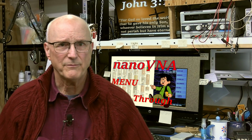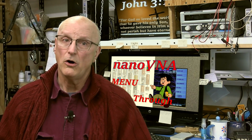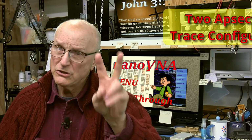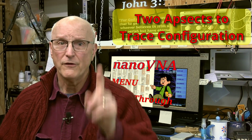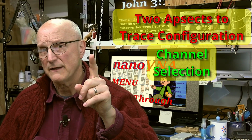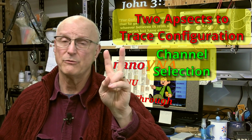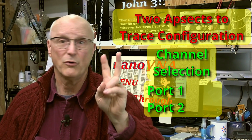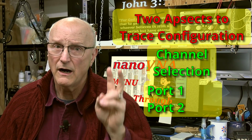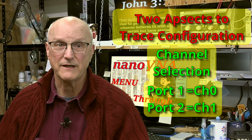Well, the next step is to configure the format of the trace, which to some degree also determines the type of measurement being made. Now there are 2 aspects to this. The first is the channel that the measurement is going to be made on. Now, there are 2 channels. On other VNAs, these are referred to as port 1 and port 2. On the nanoVNA, these same ports are referred to as channel 0 and channel 1, respectively.